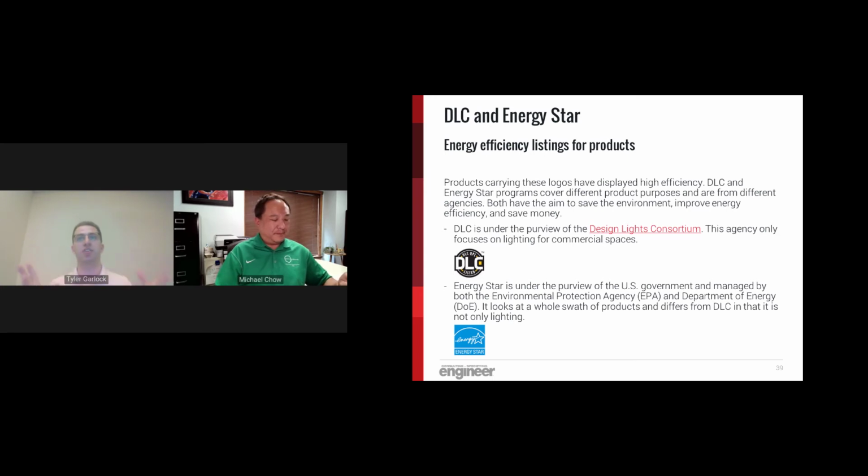But typically, it's a percentage of the total connected lighting load that has to be DLC listed. So that's the other thing to talk about with owners: even though the downlights may not be DLC listed, if the rest of the building is, you've met that percentage. So just things to think about as you're going forward.